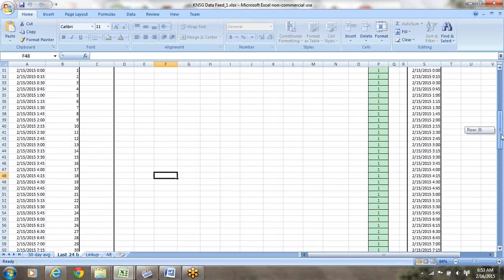Over the 24-hour period, you will see that at 9 a.m. out here, the blower has been shut down, and at 11 a.m. out here, the blower has been turned back on. That is your typical pattern. And you do not have to go back and adjust this every day because you're operating on the same pattern every day. So you just leave this alone.